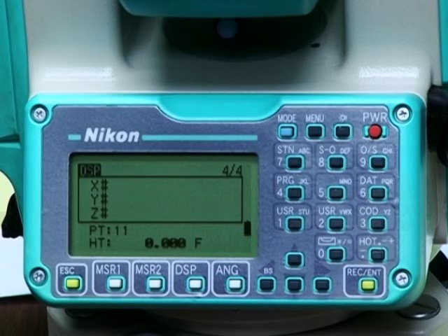It is now possible to dismantle the instrument and reinstall it at this point, and, knowing the backsight, be able to re-establish the total station relative to this grid in 3 dimensions.